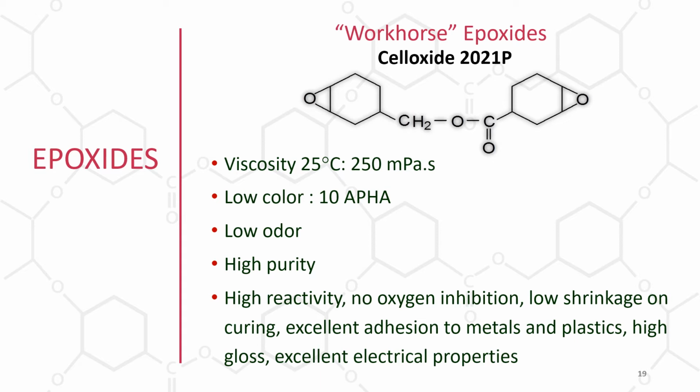So this cycloaliphatic epoxide is by far and away the most commonly used. I've seen numbers giving it between 85 and 90% of cationic cure formulations using this particular epoxide, and based on my experience, I believe that number.